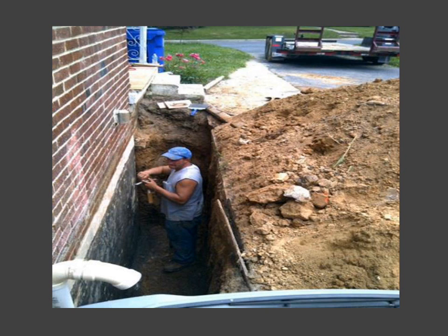Okay, here's another example that you see probably all the time. You have someone dig a trench. There are rules on how you dig a trench. You can't dig a trench that's more than 4 feet deep without doing something. This guy's got all the materials from the trench piled up on the other side of the trench. They can roll, fall in, and hit him. In addition to that, that trench could collapse.